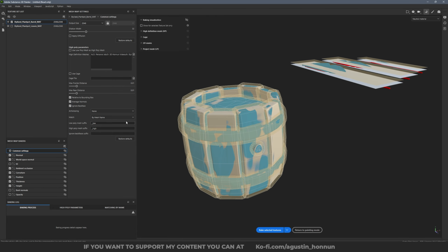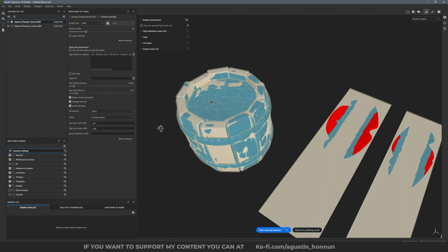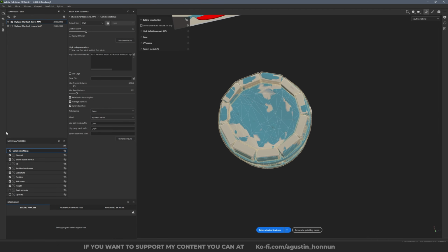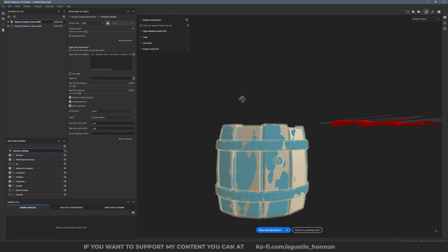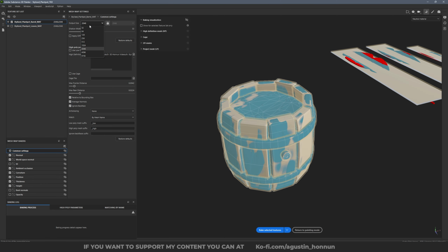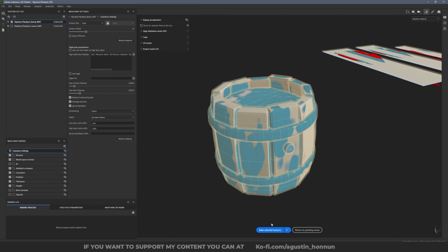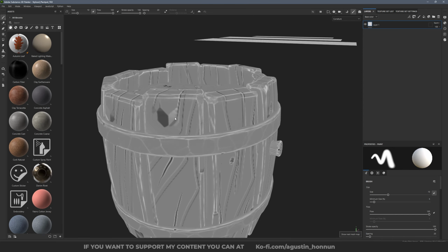So I'm going to decrease the max frontal distance until we see red. As you can see, now we don't see red. There's a little red spot in there. Make sure you don't have any other red part. Now we can increase or decrease the rear distance. I usually increase it, and that's good. I'm going to save this project first, and we can use 1K resolution output size just to test, and let's check if it works. Okay, here you see some problems.